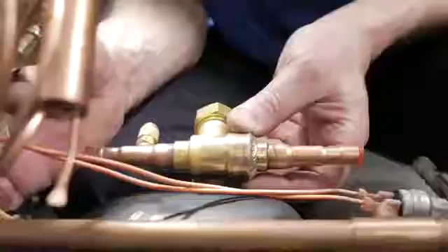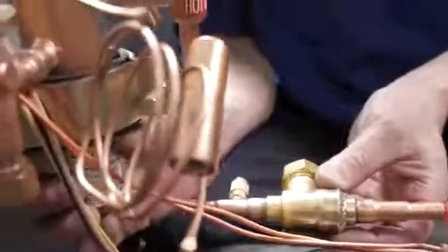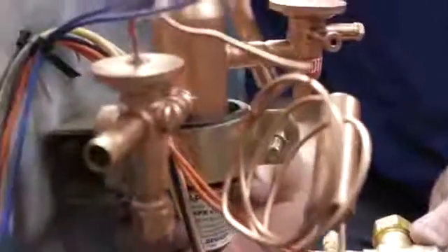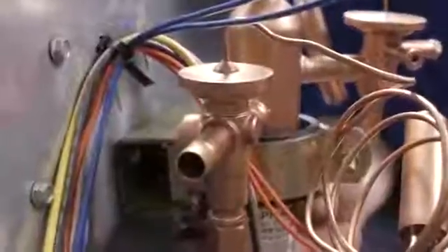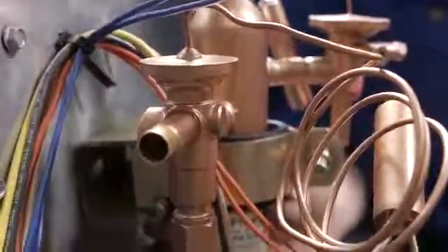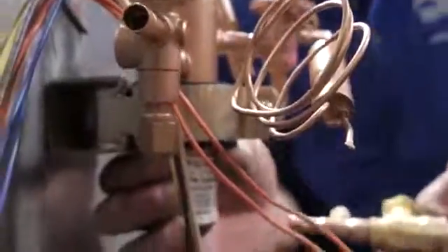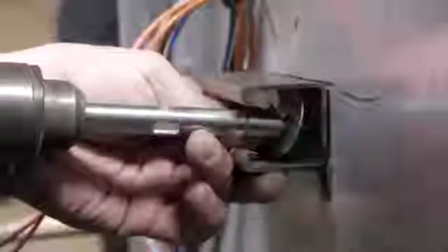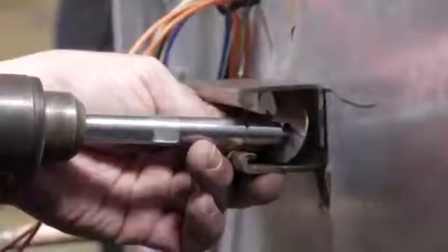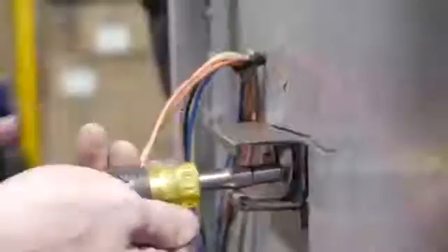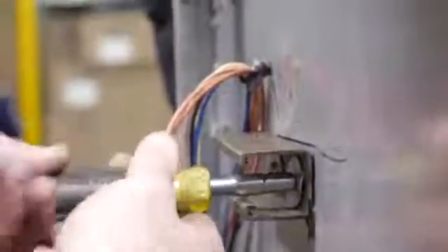It is very important to securely mount the APR control in the unit. The reason for that is the vibration of the unit and the weight of the APR control can cause potential cracks in the connection over time if left unsupported. We are going to mount the APR control to the interior wall of the unit using a tubing strut cushion clamp and a unistrut. This is just one example of how you can mount it. There are other ways.